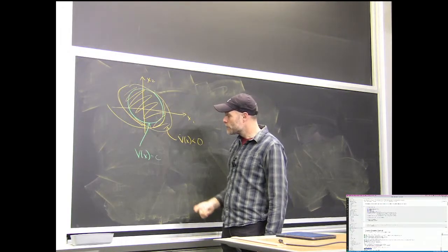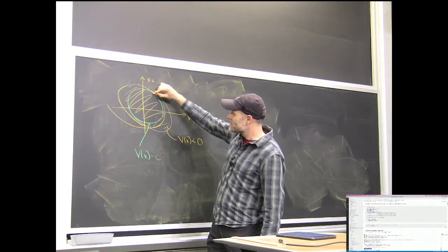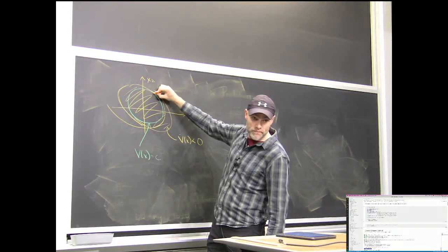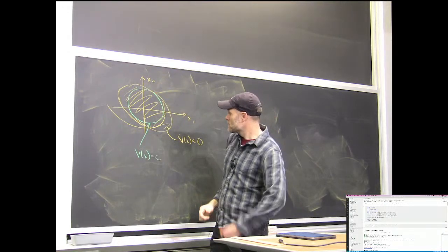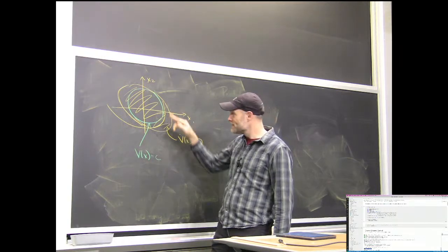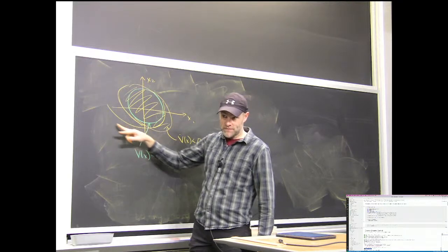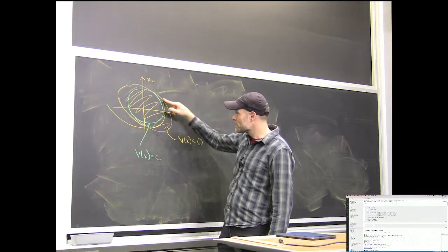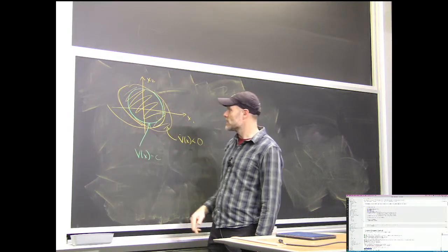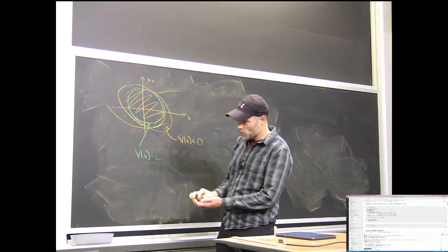Okay? You need both things to be true. You need to know that V dot is less than 0, and that I'm already inside an invariant set. V dot less than 0 by itself is not enough because you could be going downhill in your Lyapunov function, but get to a state later where you're going uphill. Unless you can guarantee that you're not going to, in a future state, go into the uphill case, then you don't have a certificate. So those two things combined work.